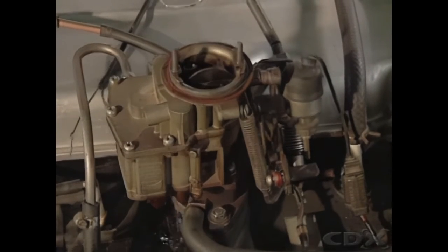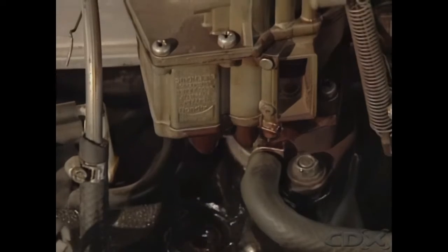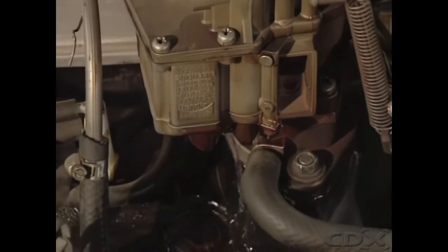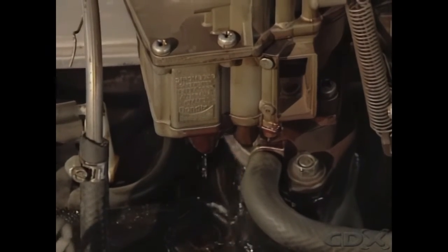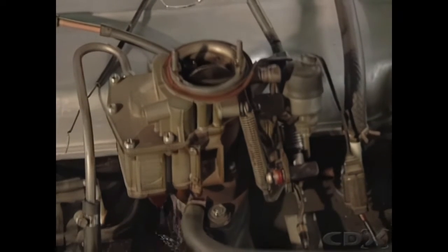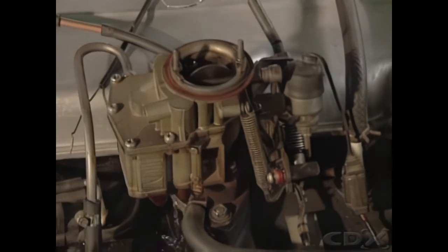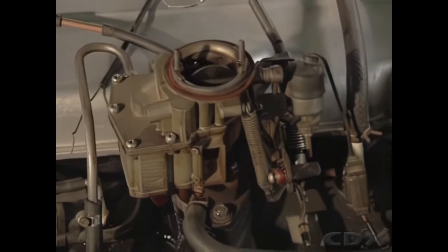Flooding a carburetor also produces rich mixtures. This can be caused by wear or by dirt trapped in the needle and seat that causes the level in the float bowl to rise and fuel to discharge from the nozzle, with little or no venturi action.